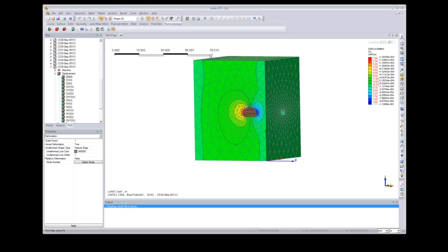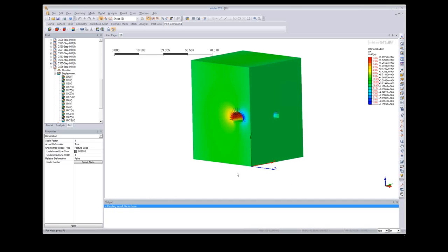If you want to make it a band, so you can see the clear band between two contours. And then also you can say no edges, or having the mesh edges, or like a feature edge. Depends on whatever you want, and you can select these visual options for making your report probably better and seeing the results.